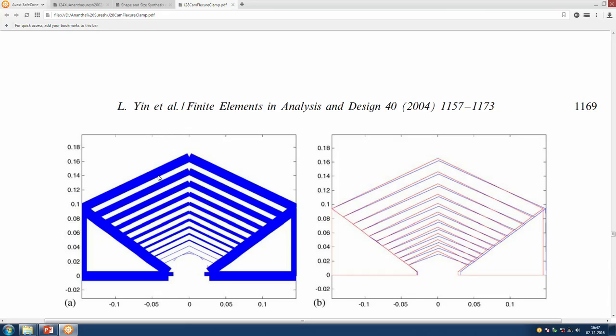Topology at least gave us how it should be connected, and then we thought, if there is one beam here and one beam here, the V beam, for the stress limit that we have, 120 KSI, how much reaction force does it get here? We computed that, and it was nowhere close to what we wanted. Then we thought that we should take more and more of them, because then the reaction force gets added up, each one of them going to that 120 KSI limit.